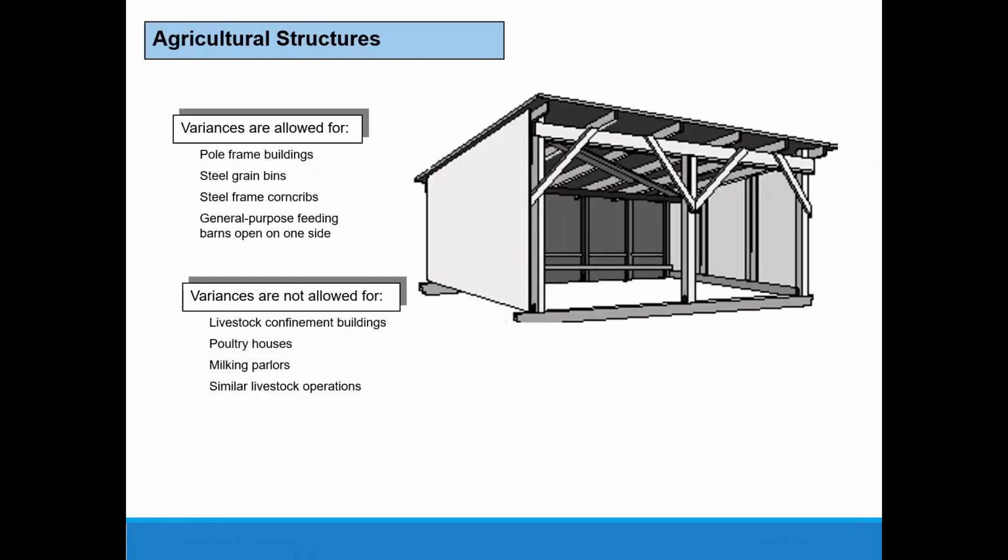And then agricultural structures are the other structures that can be wet flood proofed, and FEMA has clarified that agricultural structures have to have a variance for this, and that is because they are so variable in use and what they are that it can't just be verified by a permit alone. We have to verify that it meets the definition of an agricultural structure. And so again, it would have the same requirements of being anchored, floodproofing materials, flood vents.